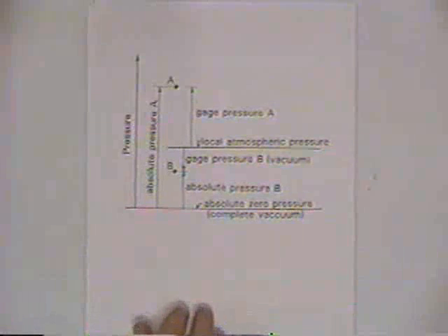Moving into pressure, as we introduce the different properties and terms we'll be working with this evening, we can measure pressure from whatever reference we'd like, and the two typical reference datums are either absolute pressure, using absolute zero as the datum, or, in many engineering applications, a majority in fact, we use atmospheric pressure as our reference datum, and we call that gauge pressure. Now, the absolute pressure is the gauge pressure plus atmospheric pressure, and we can use this diagram to visualize that.